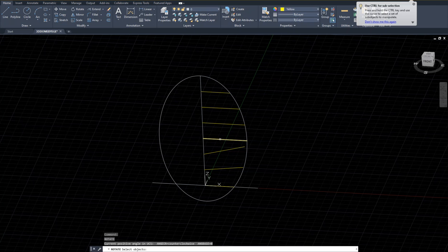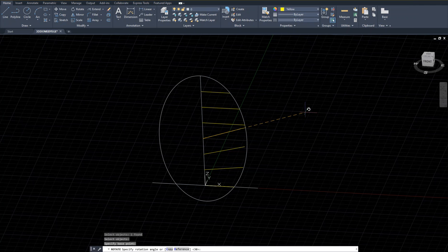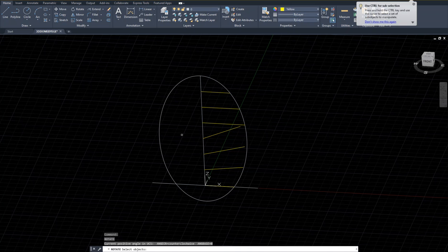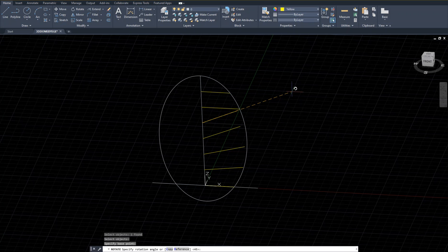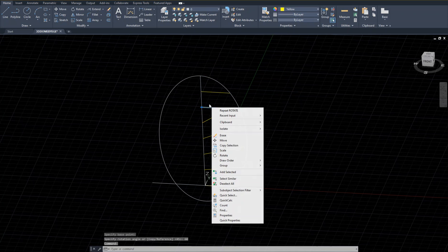Then we click on the fourth line and select the bottom of the line. The new angle is going to be 45 degrees, what comes after 30 plus 15. And enter again, the command repeats itself, click, enter, end of the line, and 45 plus 15, 60 degrees. Okay, and enter again. This is going to be the 75 degree line, click on it.